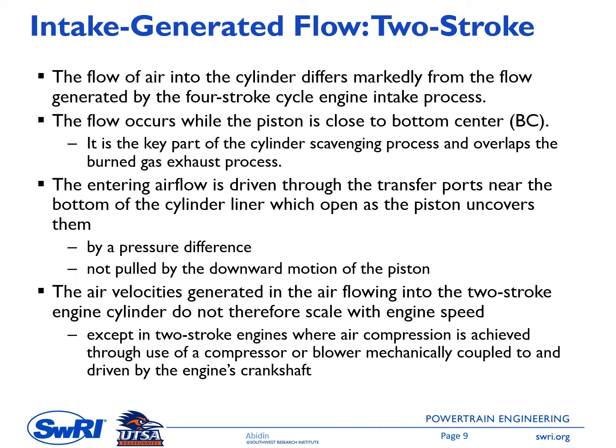Therefore, most two-stroke engines are equipped with a supercharging process, either using a centrifugal compressor or blower, or maybe crankcase supercharging.